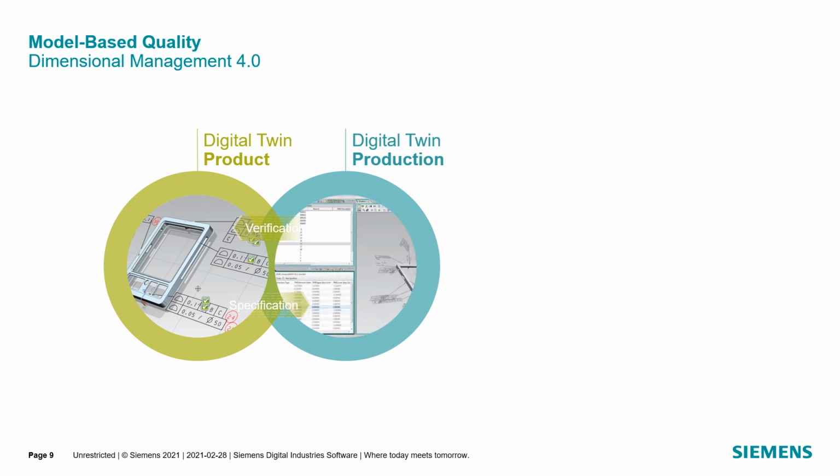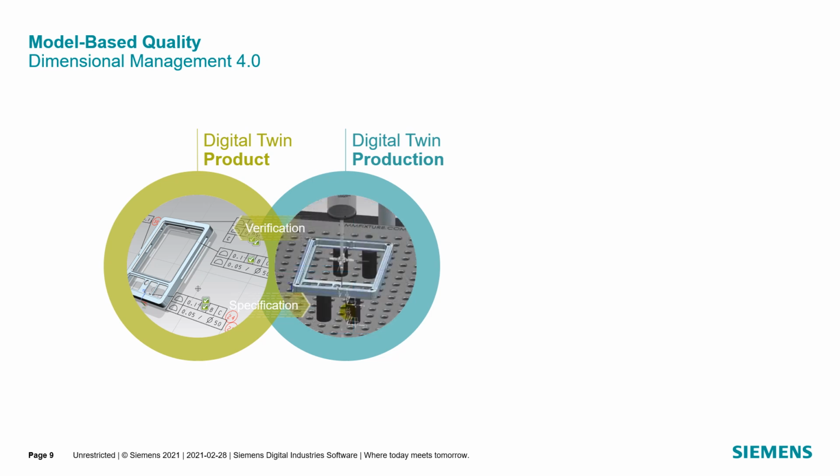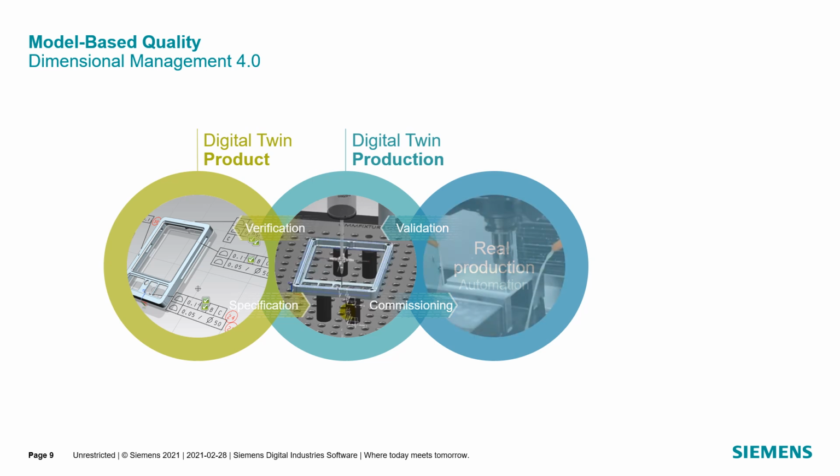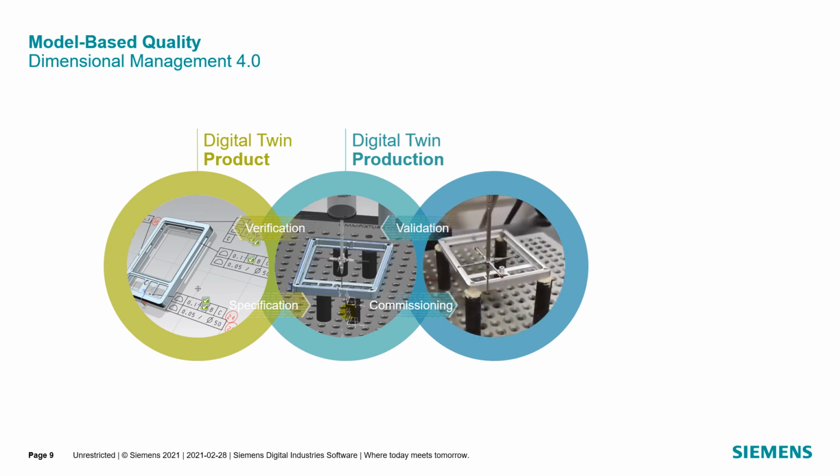Once the design is released, all downstream activities become sequential and straightforward. First of all, PMIs are extracted into Teamcenter for Lifecycle Management and Manufacturing and Inspection Planning using PMI Manager. Then CMM programs are generated directly from the master model and simulated for optimization using NX CMM. Now it's time for production execution. Parts are cut and fabricated, and inspected, all by running CNC and CMM programs previously created from the master model.